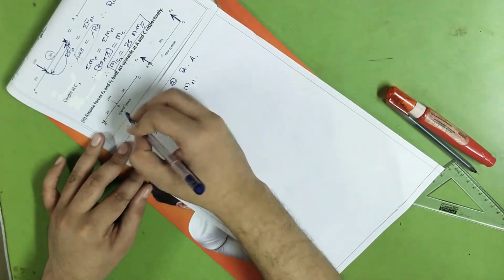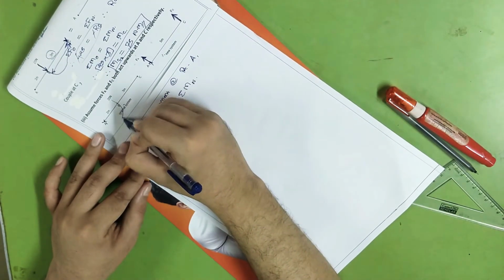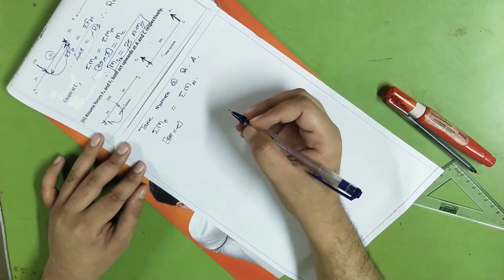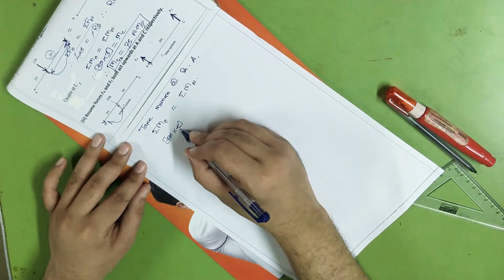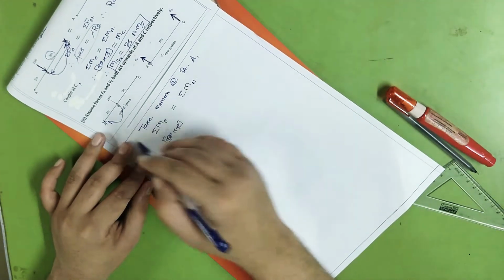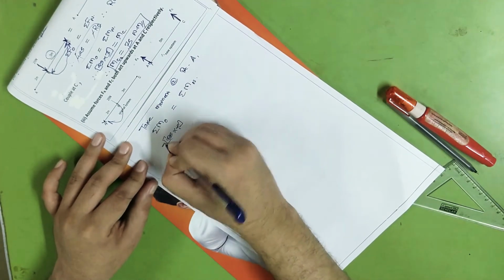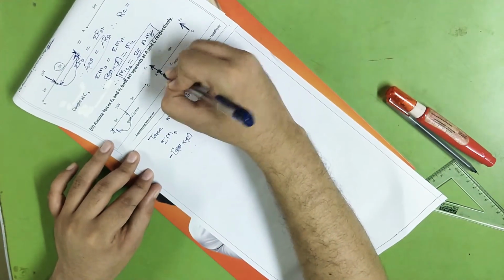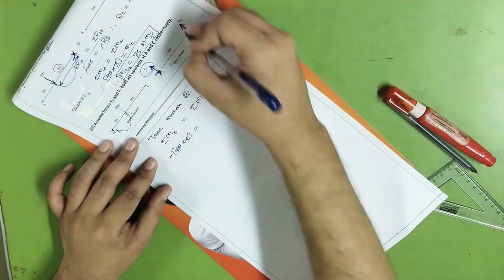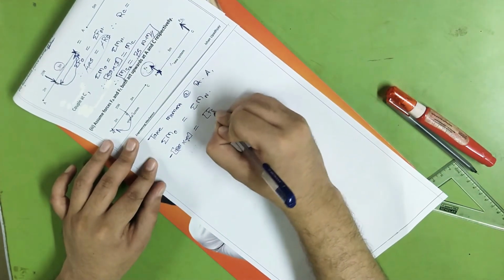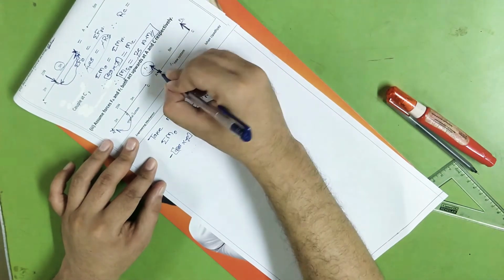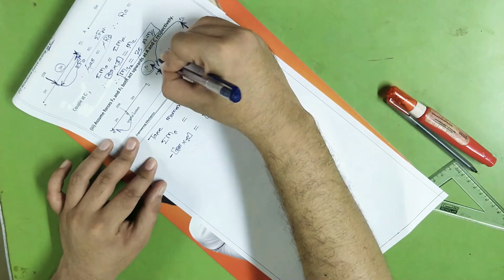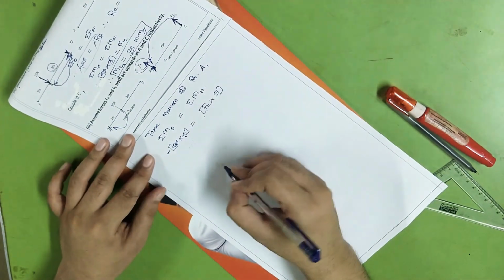Then if I'm taking moment about A, as earlier we have completed this part, it will give me moment as 25 into 2, that is 25 Newton of force acting at 2 meters away from the point about which I am taking moment, and it will produce moment in clockwise direction. So I have kept minus sign over here, is equal to, now for the new system I'll take moment about point A, so definitely FA will become 0. We are left with FC, then here we'll write FC into, what is the distance between FC and A? It is 5 meters. And it will produce moment in anti-clockwise direction, so I'll keep it plus.